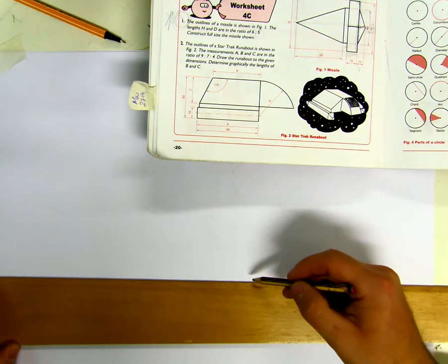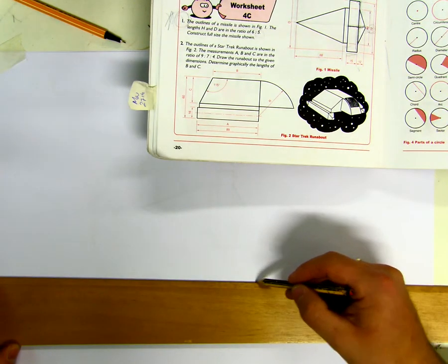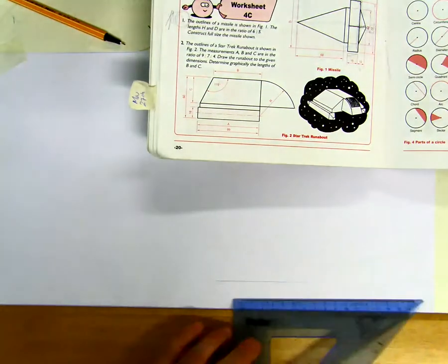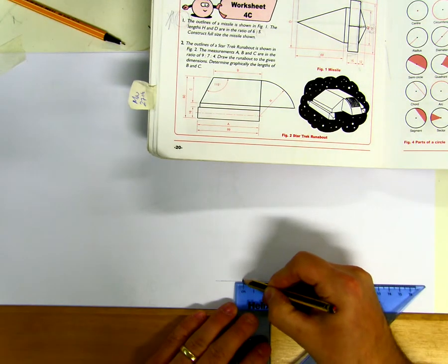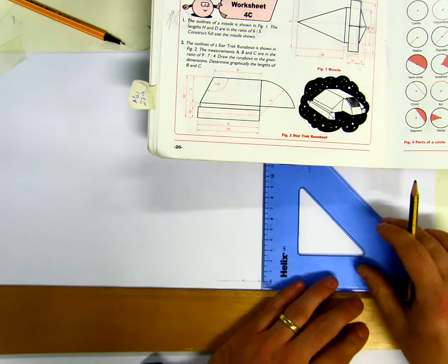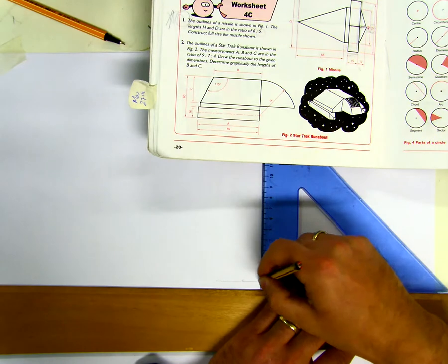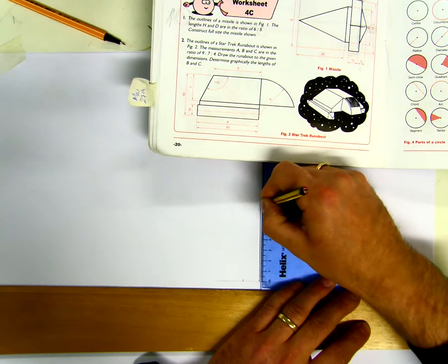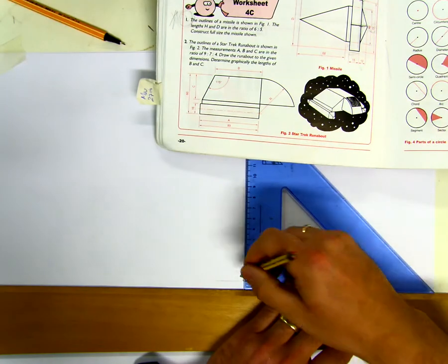First of all, I'm going to draw the line lightly, a construction line. I'm going to measure in 15 on it. 1, 5, 15. Draw construction lines up very lightly, and we know that they're going to go up 72. So I'm going to draw it up. I can heavy that in as I'm going because I know how high it's going to go. This one here, 72.